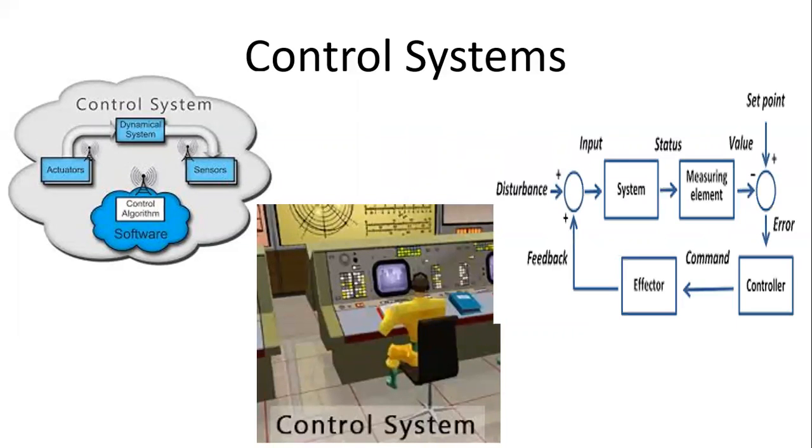The very concept of a control system is that it requires the measured discrepancy between the actual and the desired parameters. It may be noted that for accurate control of any physical variable in a process or an operation, it is important to have an accurate measurement system. Further, the accuracy of the control system cannot be better than the accuracy of measurement of the control variable.